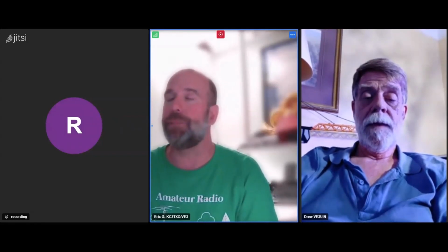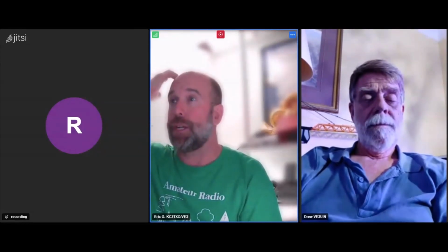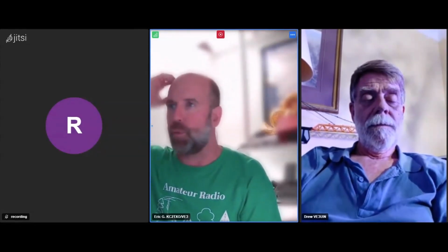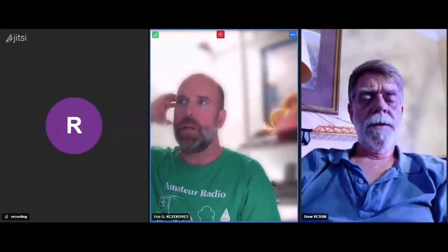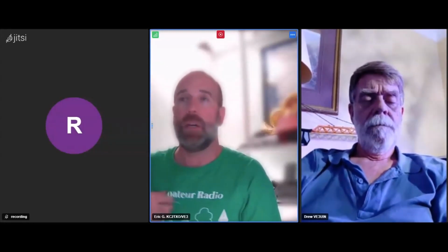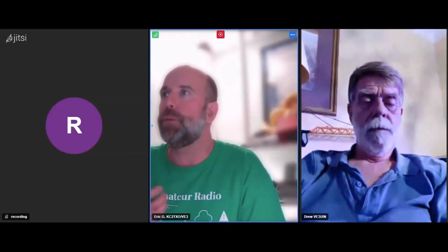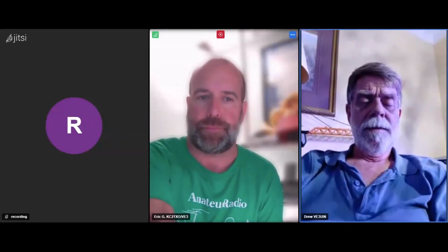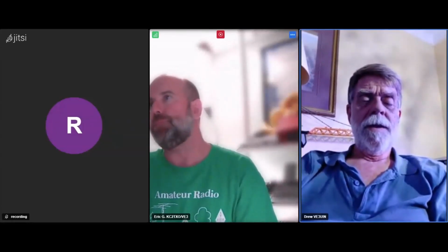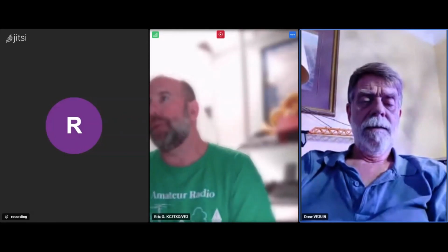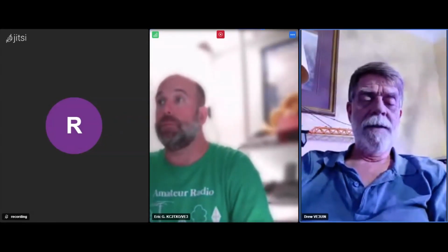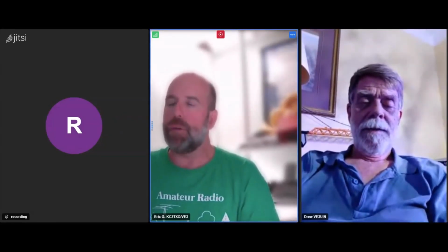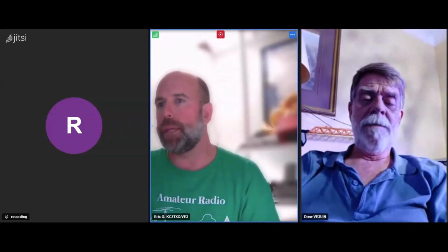So again, something fundamental has changed in my setup here, and I've got to get to the root of it, figure out what it is. So where, like you said, maybe it's a grounding issue or... same radio. Yeah, it's the 7300, right? So not the old one. 7300, and it's telling you it's putting out a full 100 watts. Yep. And do you have an SWR meter on it? Yep, it does. And, you know, it's showing that, and the meter agrees. Yeah, the meter agrees. So that part's good.